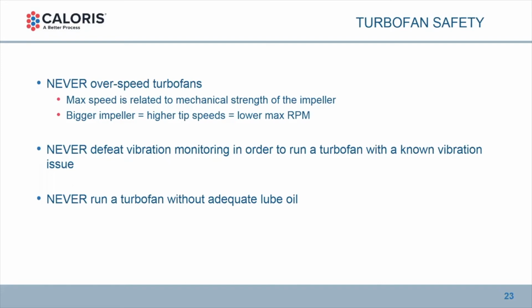And you never want to mess around with defeating the vibration monitoring of that turbofan. It's telling you information about vibration for a purpose. You need to deal with something if it's telling you it's got vibration issues. Don't disable it to keep running. And always keep an eye on the lubrication system.